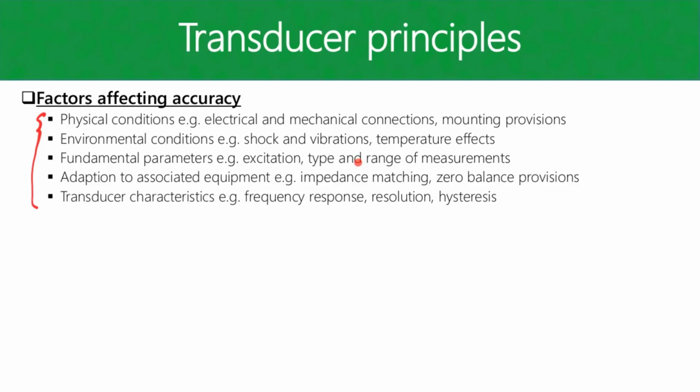So the transducer that you then have there is not going to work for that particular application. If you're going to have displacement above 5 centimeters, you are just going to read the same voltage throughout up until 10 centimeters of displacement and beyond. So your system might break and you won't know it.